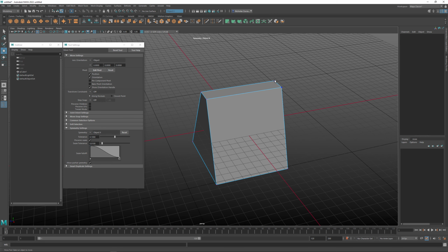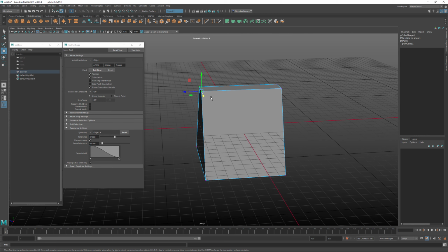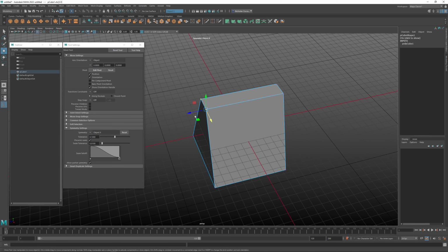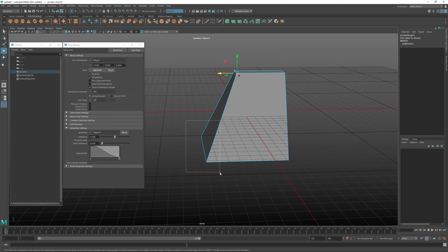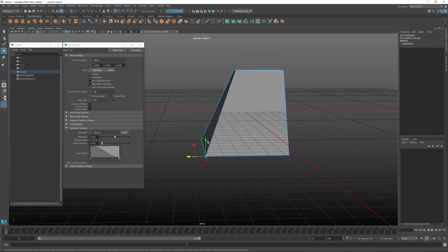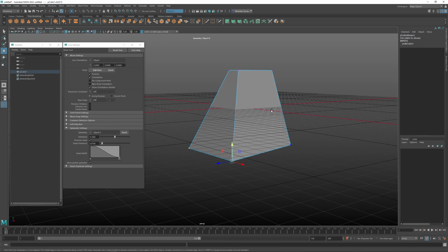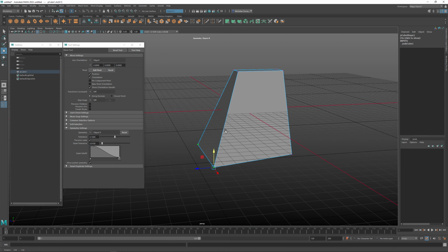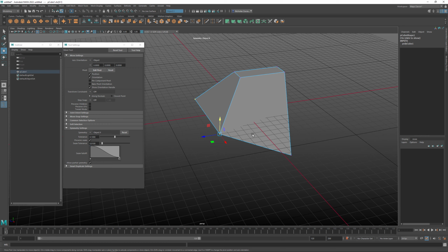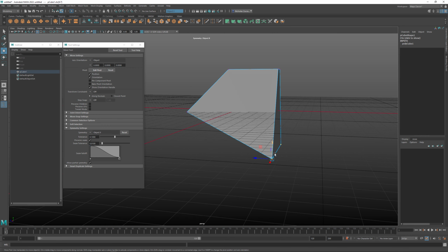And so we're able to manipulate the shape that way. We can move one vert individually at one time. If you select multiple vertices, you can move those both at the same time. So if I hold down X, I can push this back in the grid like this and start to make an interesting shape that way. If I want to bring this up to the grid up here, I can hold down X and then drag along this here, and it's going to snap. It's basically this same grid but turned, so it's invisible. You've got to just imagine that those steps are happening, but you can see it snap up to the grid like this. So I can take this as well, and then I can hold down X and then move up.